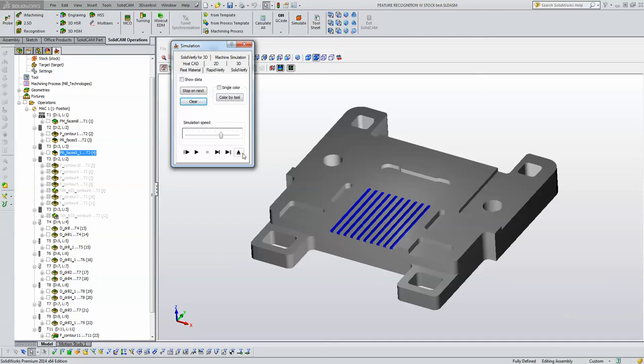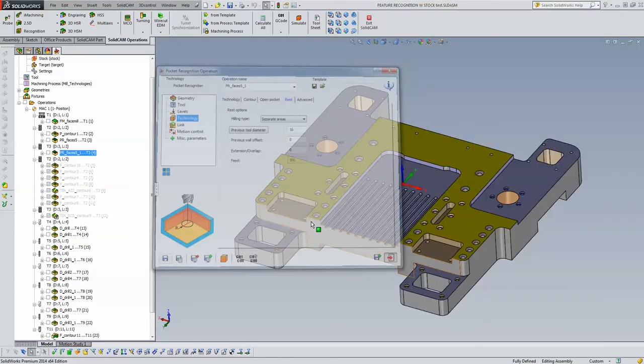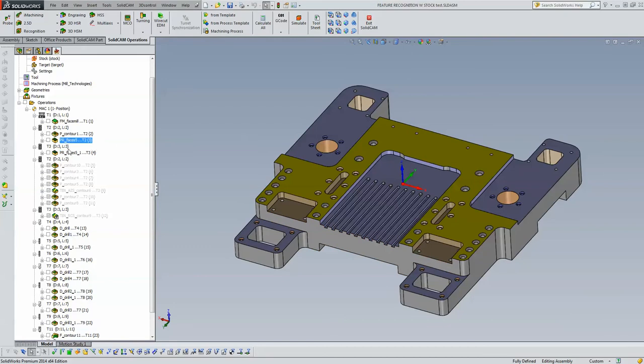Okay, so what I did here was very simple. I did two operations, one for the bulk of the pockets and one for the rest material, which was in this area over here. Two operations instead, and I did not have to choose any kind of depth over here. And this was done in two operations instead of 8 operations where I did over here.